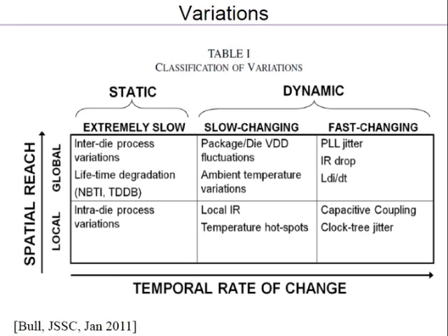You say, look, I don't know what these are, I'm going to be conservative. You want a 1 gigahertz chip, I'll design it to run at 1.2 gigahertz. You want it to run at 1 volt, you say I'll make sure it will run at 1.2 gigahertz at 0.9 volts, because there are too many things going on, I don't know. So that is the kind of margining which used to be done.